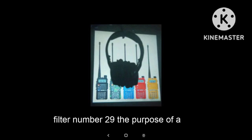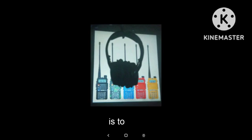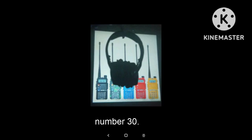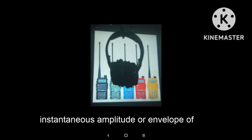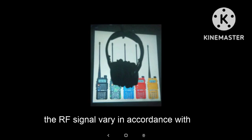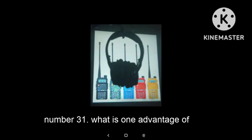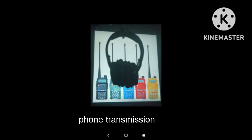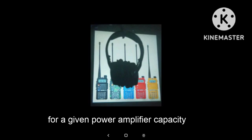Filter. Number 29. The purpose of a balanced modulator in an SSB transmitter is to suppress the carrier and pass on the two sidebands. Number 30. In what emission type does the instantaneous amplitude, or envelope, of the RF signal vary in accordance with the modulating audio? Amplitude modulation. Number 31. What is one advantage of carrier suppression in a double sideband phone transmission? More power can be put into the sidebands for a given power amplifier capacity.